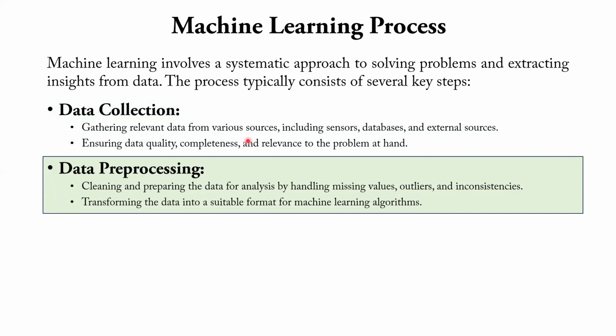So next one is data pre-processing. Already we discussed handling missing data and outliers. Another thing is outliers. Outliers are the points which are far away from the regular points. Generally some mistake or defect while fabricating makes the tensile strength or hardness go away from the actual value. These outliers cause poor performance of the model because they increase the error. After running the data, if any outliers are increasing the errors, we can detect those points and retest whether it is really that value or a mistake happened, so that after rectification of the outliers, we can increase the performance of the model.